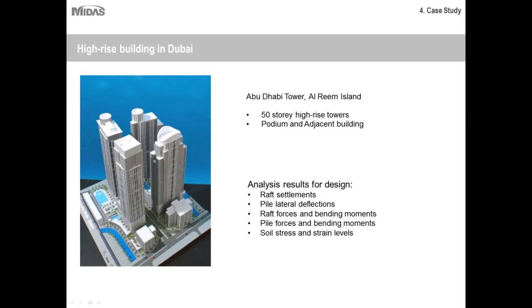for these raft foundations. And as we talked about this previously, it's a high-rise building. It will have huge wind loads or lateral loads effect, and this again calls for a raft foundation. So irrespective of the soil strata here, the loading condition and the structure type and the field conditions forced engineers to use pile raft foundation, or I should say pile raft foundation was the optimal solution for the engineers dealing with this type of project.